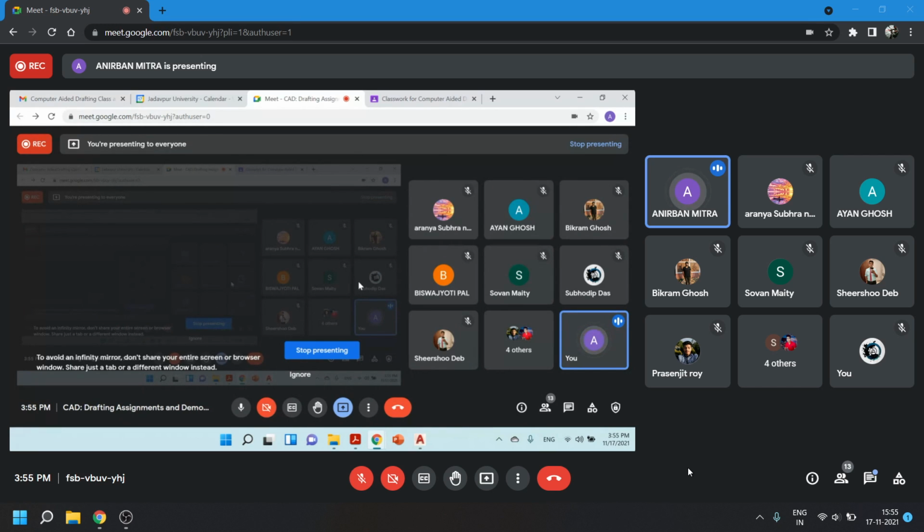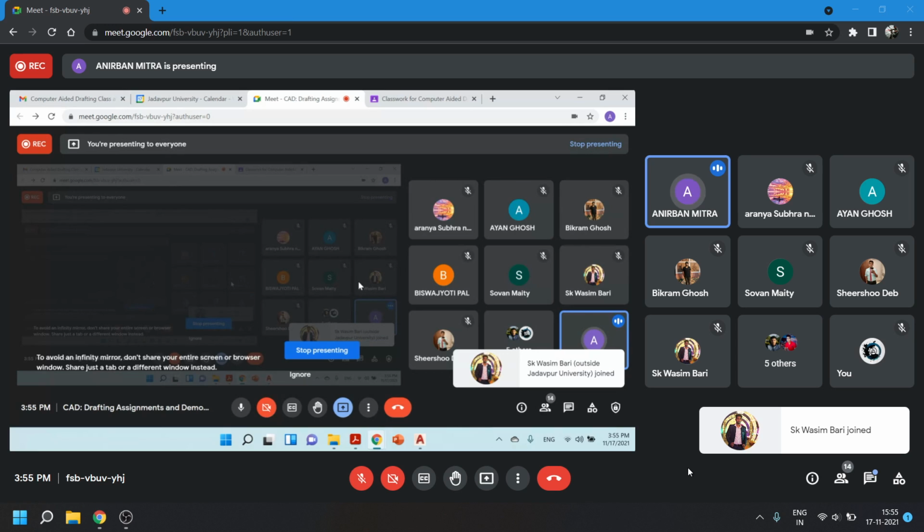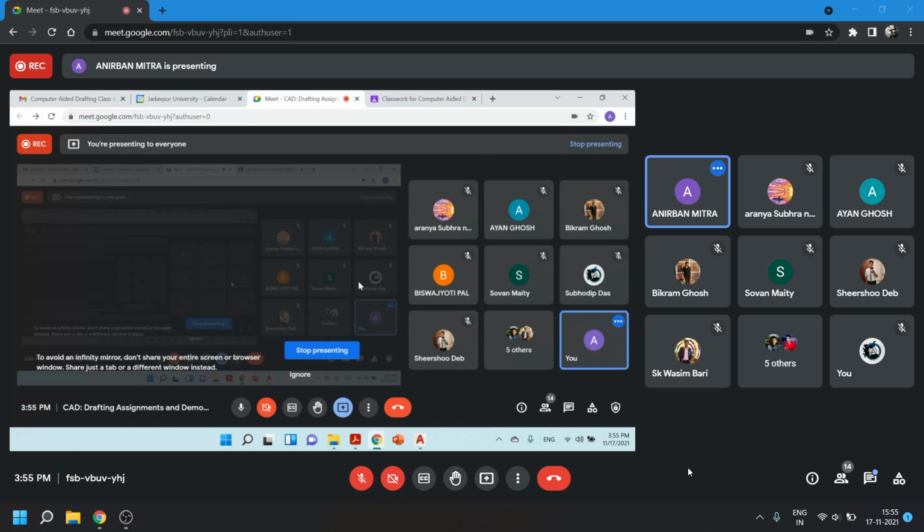That tolerance has to be provided by the designer. At the beginning itself, the designer would give an acceptable tolerance range, say 15 plus minus 0.02. That means 14.98 to 15.02 is acceptable. If any component is less or more than that in dimension, then it is rejected in quality. So that is the concept of tolerances, and those tolerances can also be given in AutoCAD.